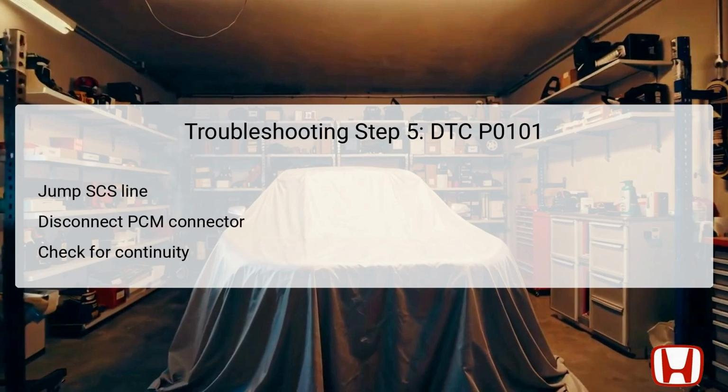In the fifth step, you must jump the SCS service connector switch line using the HDS and allow it to sit for more than 1 minute. This allows the diagnostic systems to reset and accurately capture new measurements. After this, disconnect the PCM connector B51P.